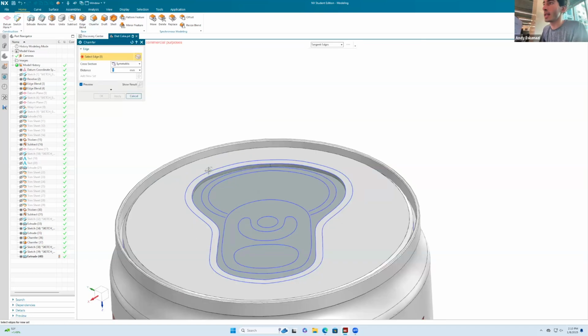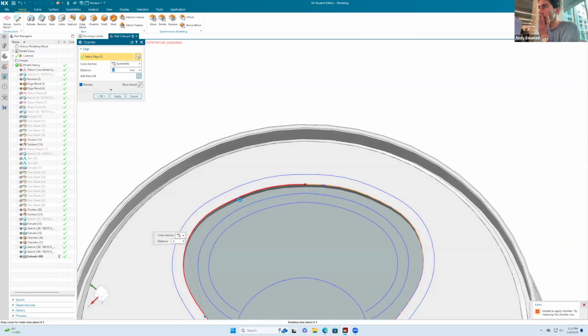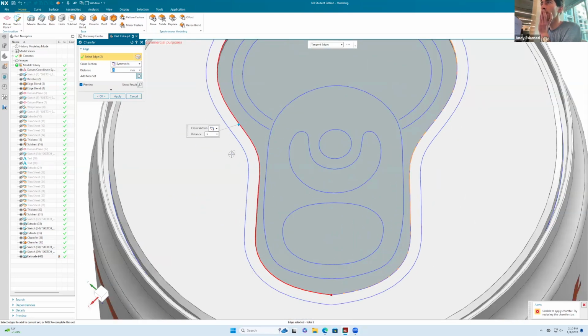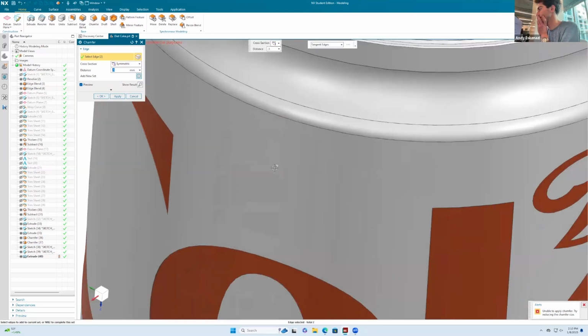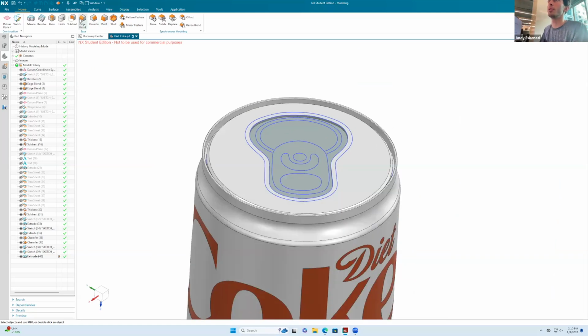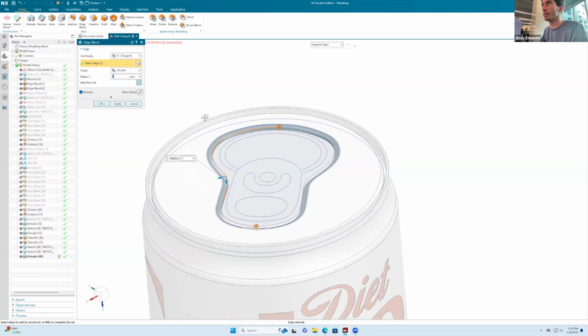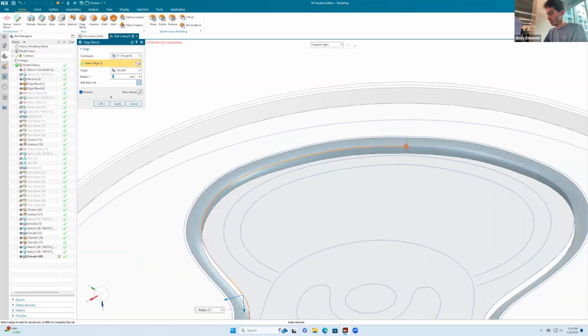Okay, and now we can actually chamfer these edges by say 0.5. Does this work? And then transition chamfer size. Actually, let's see maybe we did edge blend. Okay, that does work a lot better. And one.